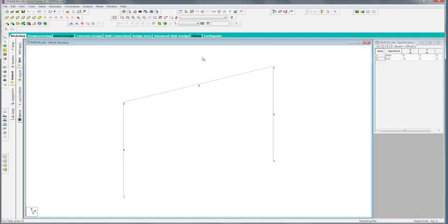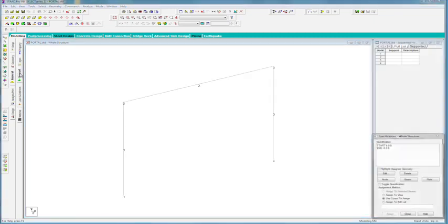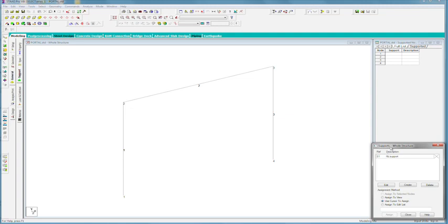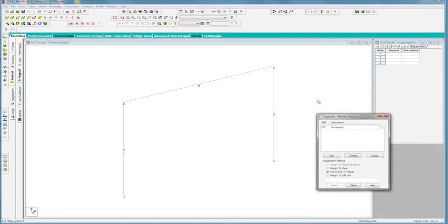Okay, by the way, we're now at section 1.5.8 if you're looking at help or if you've printed that out. And it's time to specify the supports. You recall from the initial picture that one of them, support node 1, is fixed and node 4 is pinned. So to create a support, we need to select the support page, and that's right here, the icon, or as usual we can go to General, Support, and get the support page necessary to create our supports.